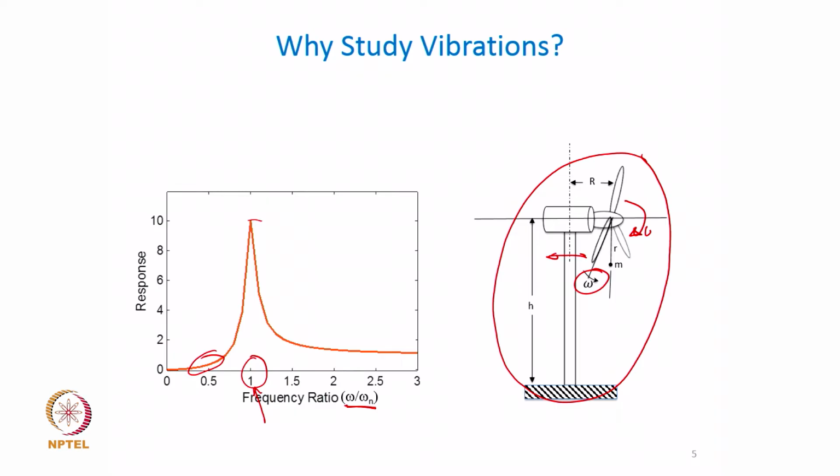So, the point is, if you design this column based on only the stresses which you anticipate based on certain rotational speed, certain amount of unbalance in the rotor, and think that those are the stresses that will be actually encountered, we need to be a little careful in assessing the stress pattern or the stress level in any vibratory system, any dynamic system like this.